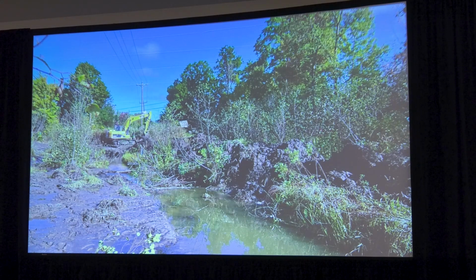And then you see the contractor working their way out on the other side of the channel. They had baled extra material across the river so that all that material was on the road side of the river. So as they were able to walk out, they were able to bail that material behind them. But this was a spot where they needed to be completely done at a location before they got further away than they could reach, because there was no way to get back out there. It was way too wet, way too soft of soils.